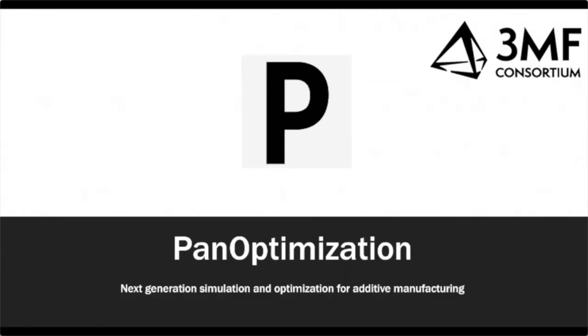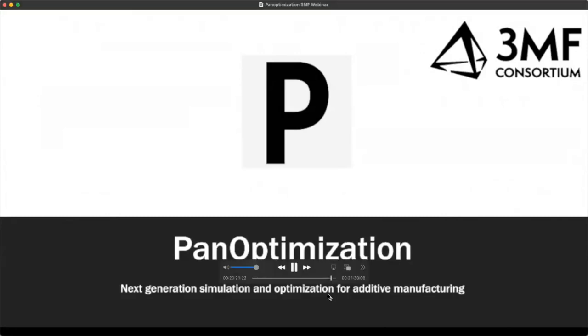Yeah, we recently did a webinar with Additive Flow, who used the 3MF volumetric format, which is, in this case, a bitmap stack, which represents the voxels for each layer, so they can modify the build parameters within each component and have a gradient between different parameters in different areas for different requirements. So I think that might be the way to go, hopefully, in the future, if everyone's using the same format for that.